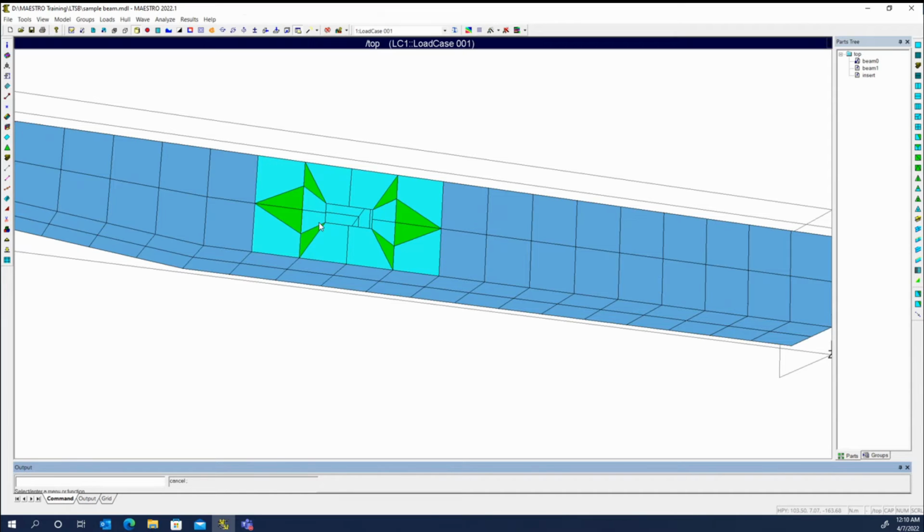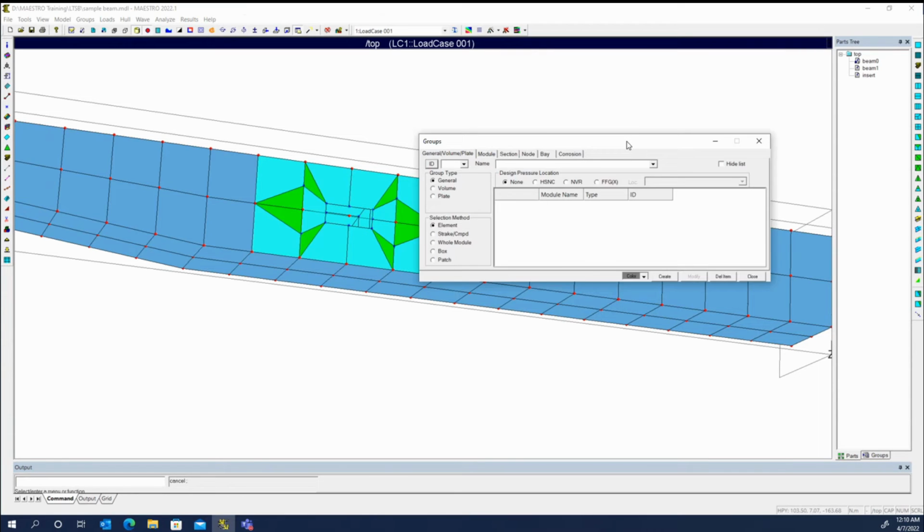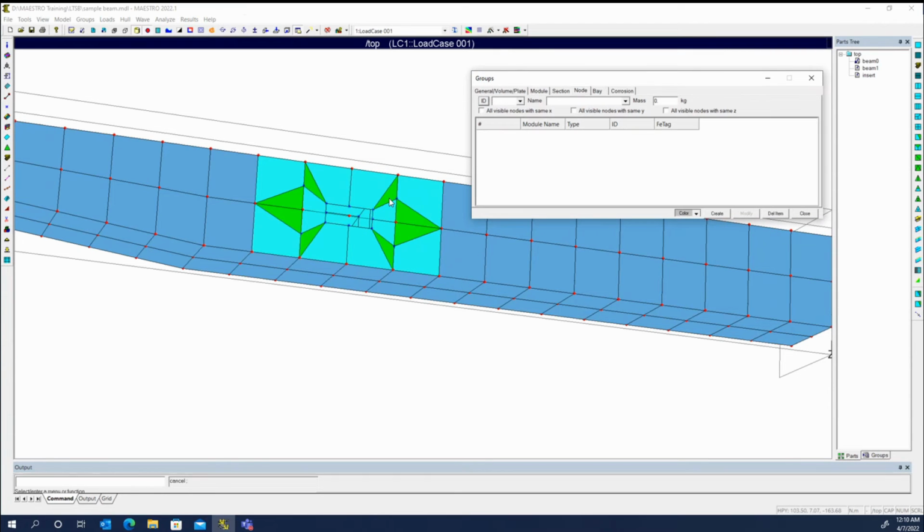Now I have the geometry layout that I want, but things aren't lined up very well. So we can turn on nodes and additional points. And then in the node dialog, we can select these points. And if you click on one side and click on the other, I like to click near a node, but on the element, and it kind of goes from that direction and selects the node associated with this element.